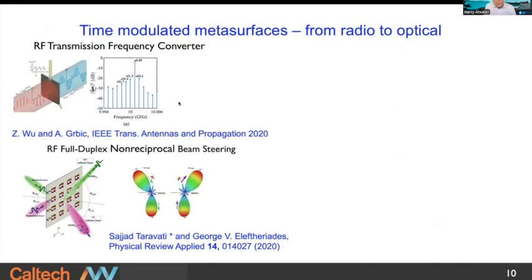That's because we can drive electronics at RF frequencies to precisely tailor the temporal waveform. This principle was carried out in a very elegant fashion to perform not only spread spectrum multiplexing, but also non-reciprocal beam steering, which requires careful control of the temporal waveform.